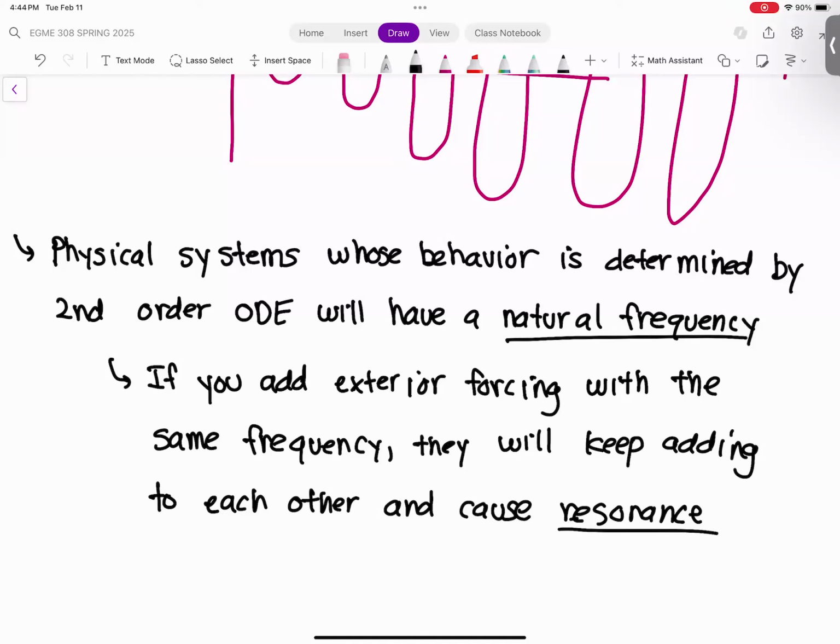Okay, any questions on resonance here? All right, so the homework problem, homework 4 on homework 2, asks you some questions about resonance. If you're designing a building, one thing that occurs in California specifically is earthquakes. Earthquakes are a prime example of an oscillatory loading, right? So when you're designing a building, you want to make sure that the natural frequencies of the building don't match the common frequencies that occur in earthquakes. Otherwise, your building is at risk of earthquake failure.